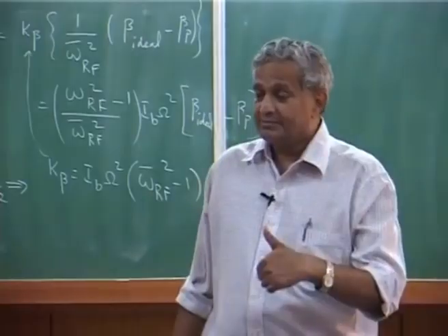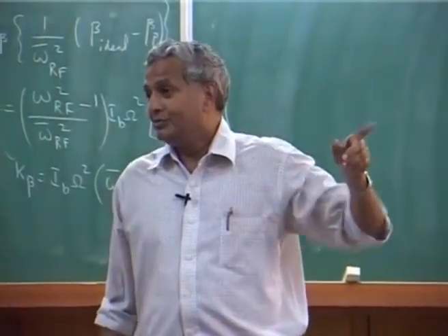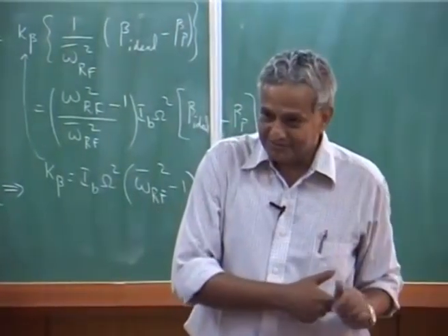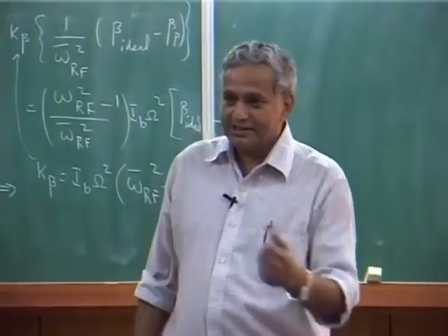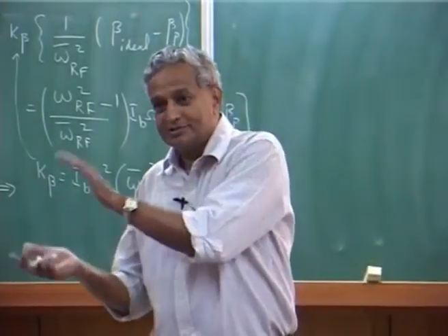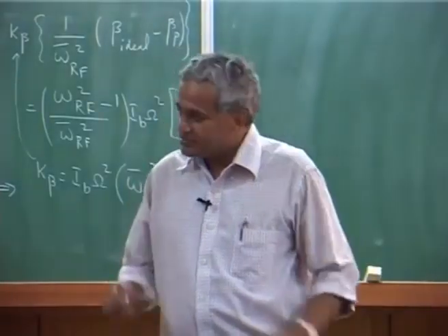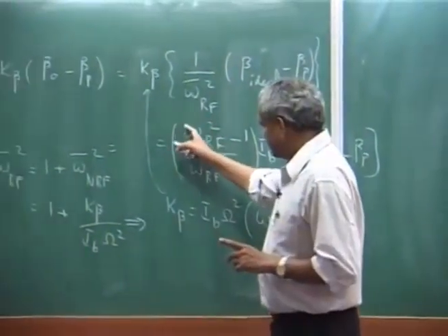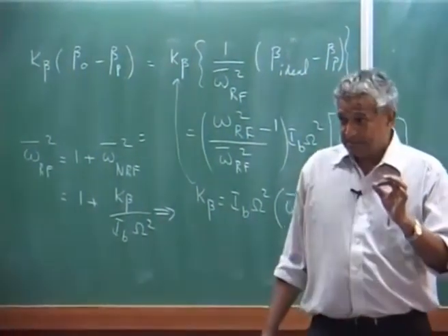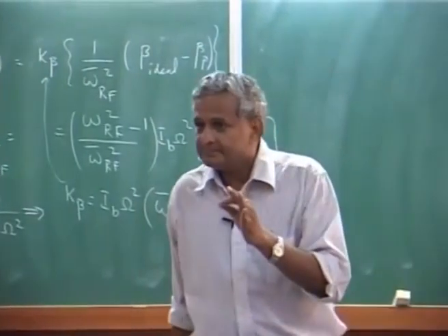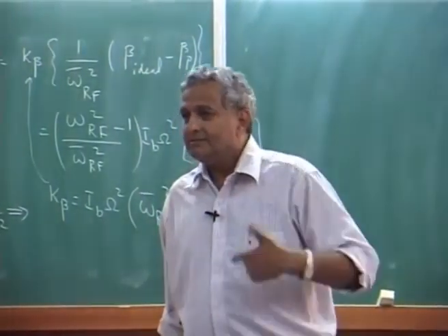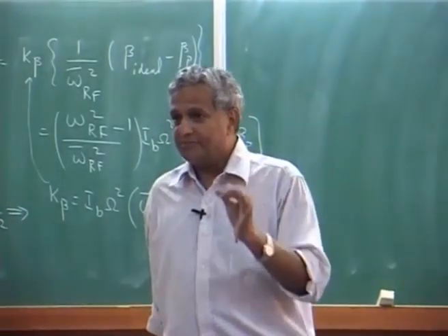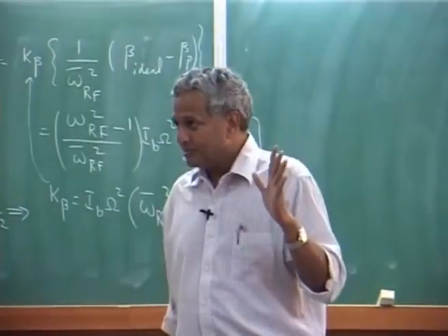But at the same time, you do not want the blade to have lot of root moment from a structural design point of view. On one hand you want a highly agile one, but on the other hand you do not want the structure to be very big. So, this is a trade off. Finally, that is why the design of rotating flap frequency to have a particular number is very interesting and very important in the helicopter design. What flap frequency you will keep for your helicopter. Okay.